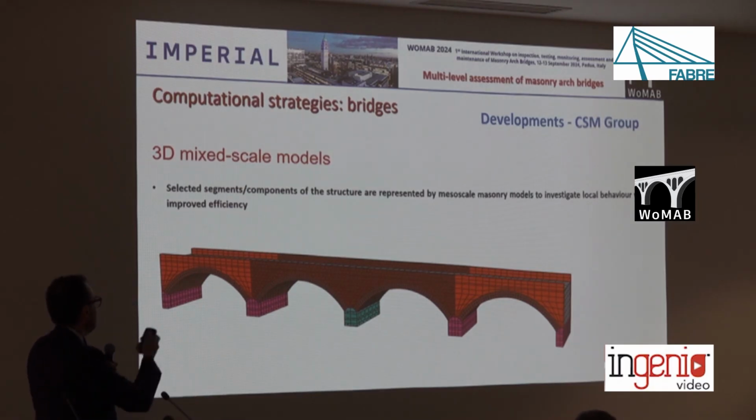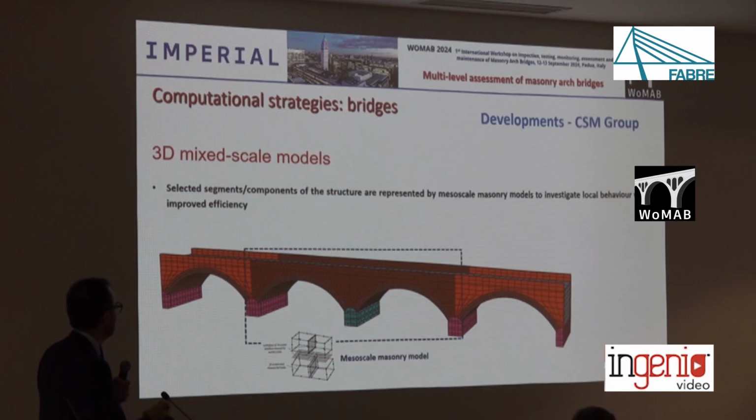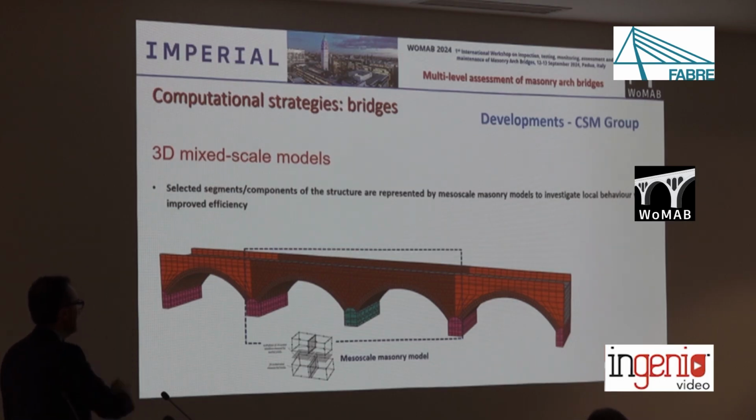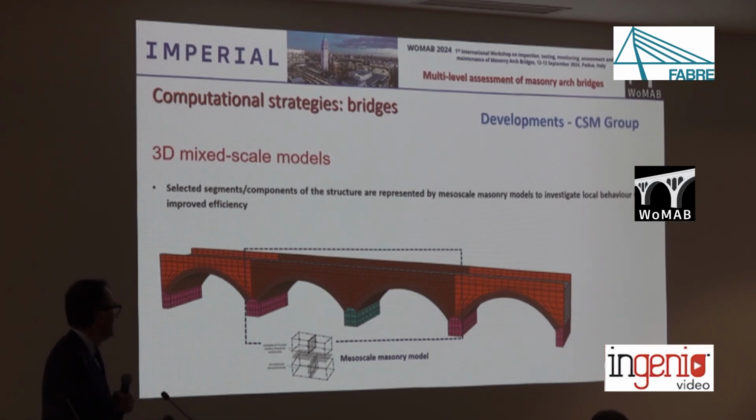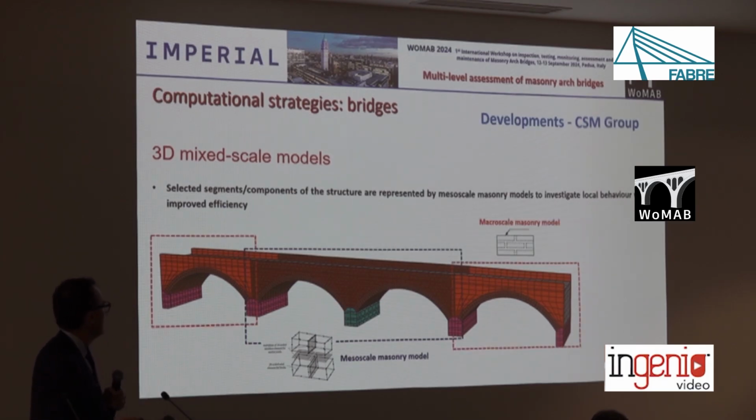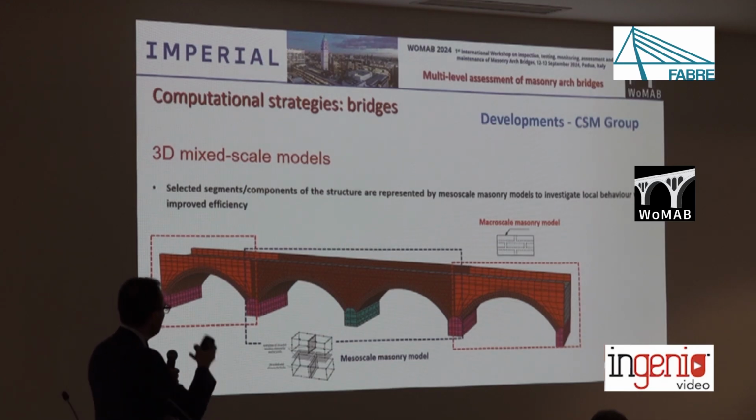We developed our methods in combination. When we deal with a large structure and we want to focus on a specific section of the structure, we can adopt a mesoscale approach, and the remaining parts of the structure can be modeled using a more standard macroscale method. This is needed especially when we deal with large viaducts.